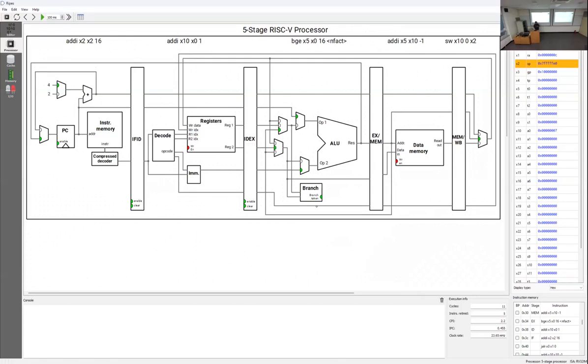So there is a dedicated branch unit here. This architecture is a little bit different. So what will happen? The branch is taken, so the correct instruction is fetched in the instruction fetch stage. But as I mentioned, the instructions in the ID stage and the instruction fetch stage are incorrect instructions. So those instructions need to be flushed. Flush means in the toilet.